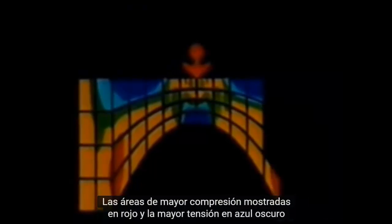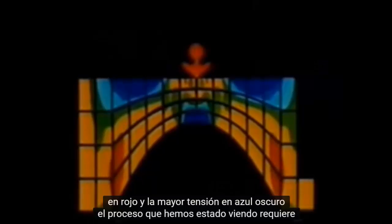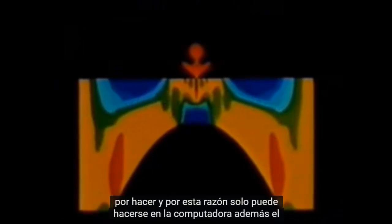In this example, we're showing the stresses as a contour diagram, with the areas of greatest compression shown in red and greatest tension in dark blue. The process we've been watching requires vast numbers of individual calculations to be done, and for this reason can only be done on the computer. Furthermore, the calculations usually involve such large matrices that a powerful computer with a large core store is needed.